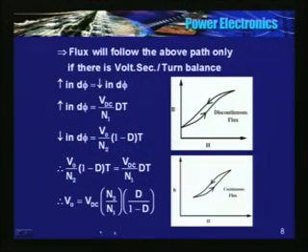There is the isolation, and the transfer function is the same as the buck boost converter. In this transfer function you can see that V0 and VDC can be greatly different, because I will choose a suitable ratio. By suitably selecting this ratio, the magnitudes of V0 and VDC can be anything; they can be greatly different.